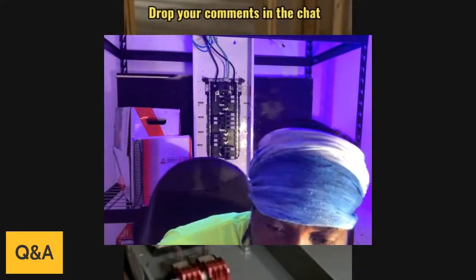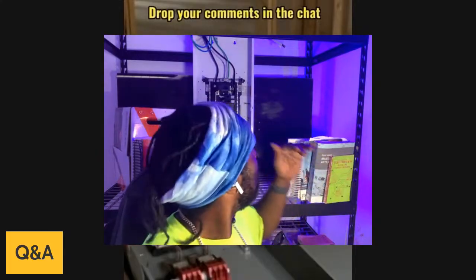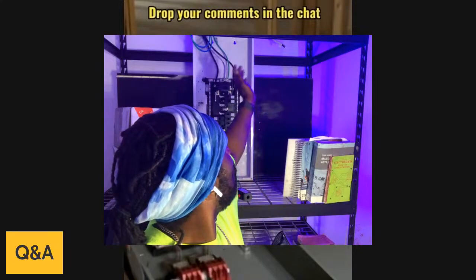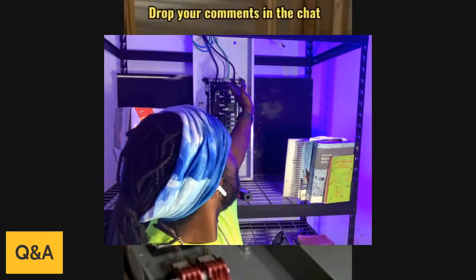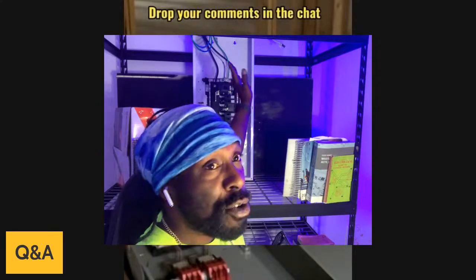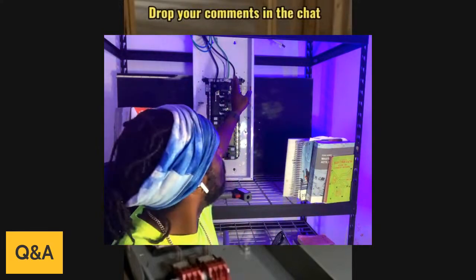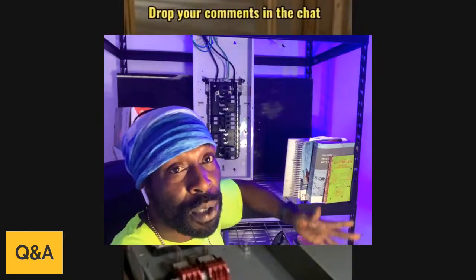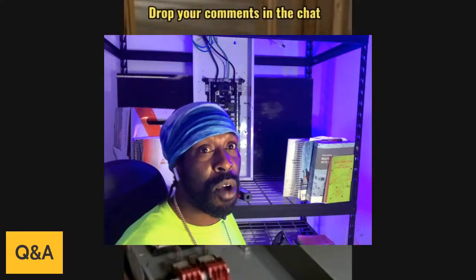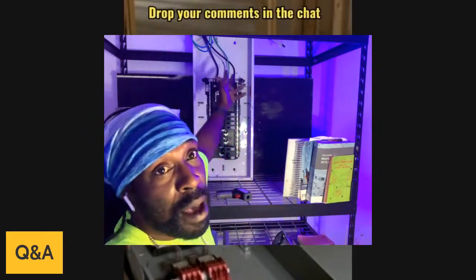So we're going to head over to the panel that got installed here. This is a 125 amp panel, okay? And as you can see, the way I fed my wires, I came down, you've got the green cable, which is for the actual bonding if you're going to be coming in from underground. Your underground service usually requires a ground wire. You put your ground plate underground and then you pretty much come off of your ground plate and come into the panel.